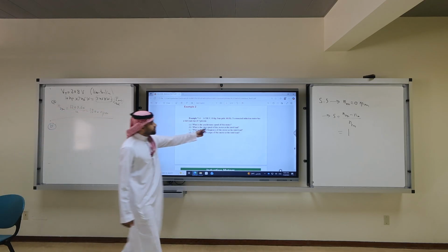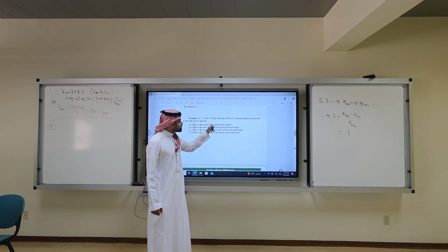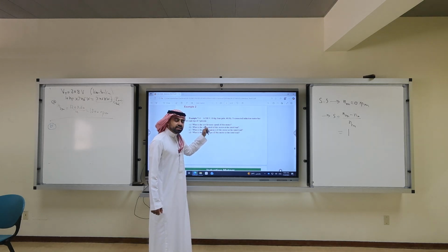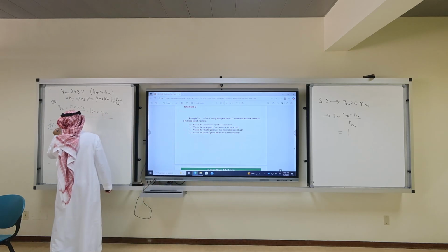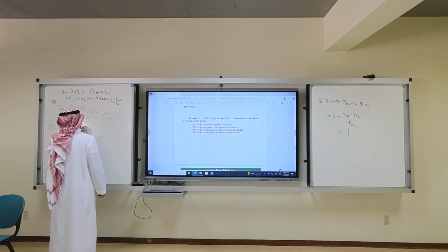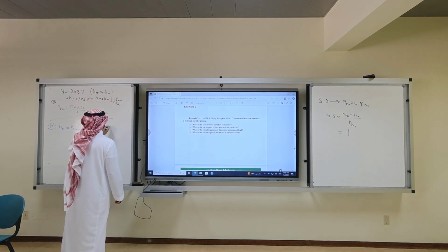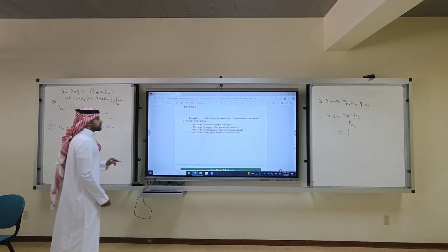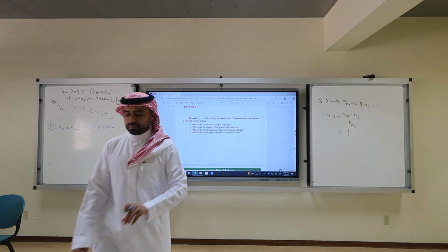What is the rotor speed of this motor at rated load? Rotor speed, is it mechanical speed or electric frequency? يسأل عنه. Mechanical speed. So it is what? N sub M, which is N sync times 1 minus S, which is 0.95 times 1800, which is what? Calculators. 1710.